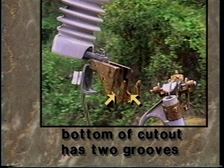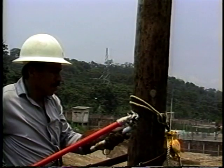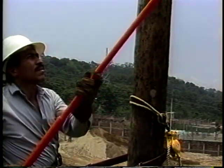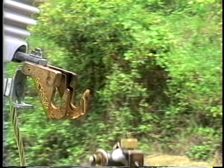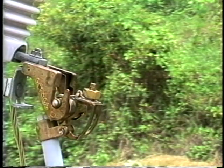Installation of the barrel into the cutout. The bottom of the cutout has two grooves that should be aligned with the guides on the barrel. Hold the barrel in your hand with the cap pointed toward the ground. Place the finger of the hot stick in the upper eye of the barrel and raise it toward the cutout. The guides on the barrel should be aligned with the grooves on the lower portion of the cutout.